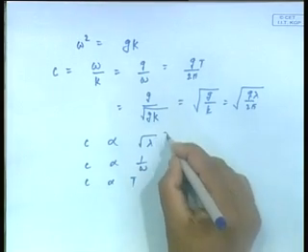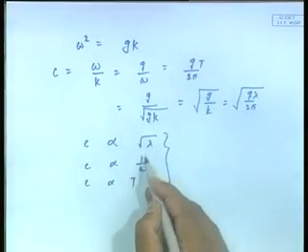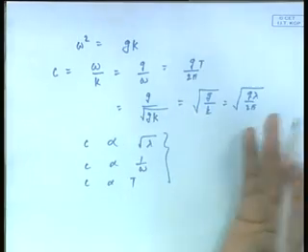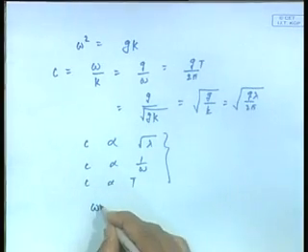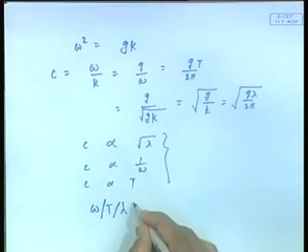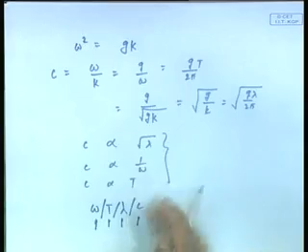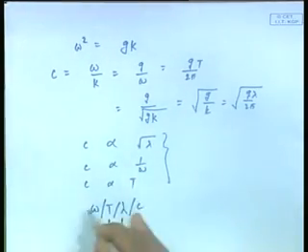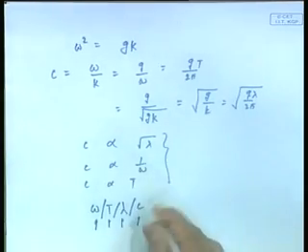Okay. So, this tells us that the celerity of a water wave, or phase speed, depends on length, and of course, length and frequency are connected. Therefore, it depends on length or period or frequency, which means that in deep water, and also in shallow water for a given h, if I were to tell omega or T or lambda or c, all of them would immediately relate to each other. There can be only one value for each of these. So, you cannot have, for example, two different wavelengths travelling at two different speeds.